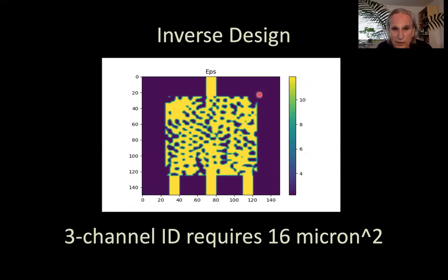Inverse design is just getting going. Inverse design, instead of using a physical principle, you use a layout, you write Maxwell's equations, just like you do in some of these brute force solvers that are being used now, and you put on some optimization criteria, you let it optimize. Here we have a three-channel multiplexer over here, and this three-channel multiplexer is 4 micron by 4 micron. If you tried to scale that using the scaling laws, you'd find out that you could make this in like 50 or 100 microns squared.